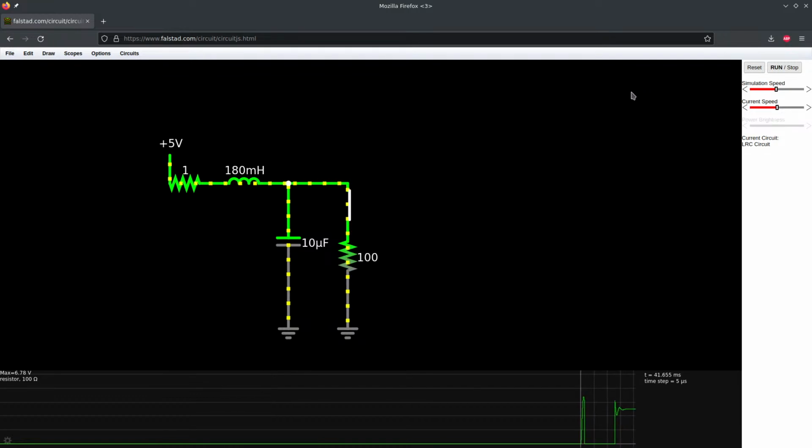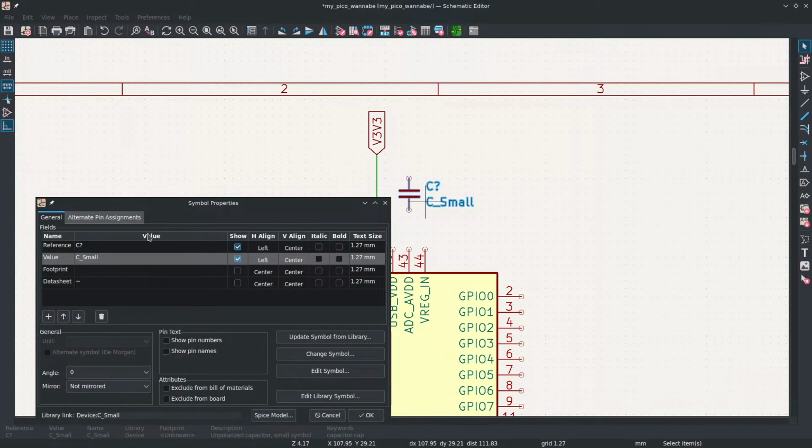I don't know if that was super clear or not, but it's important, and it helps reduce this sort of dip that you get right here, if you can see. Right at the time of switching, you get this little dip, and if that goes too low, it could cause problems in your chip. So just provide clean power, and it boils down to follow what it says to do on the data sheet, and it almost always is just a 100 nanofarad capacitor at every pin. Unless it's like a power device, in which case it's more. So, anyways, we're just going to do 100N.